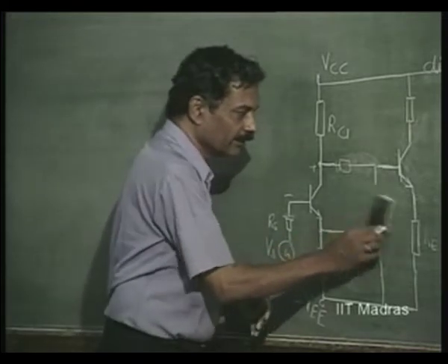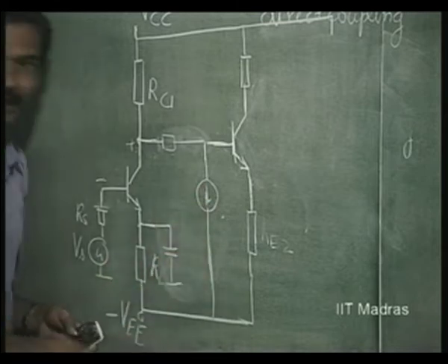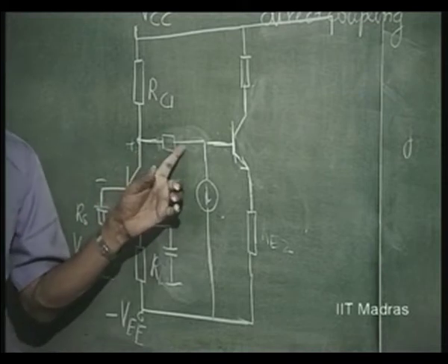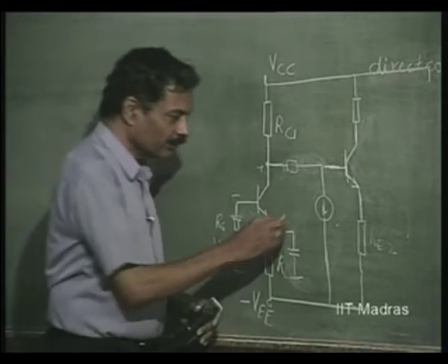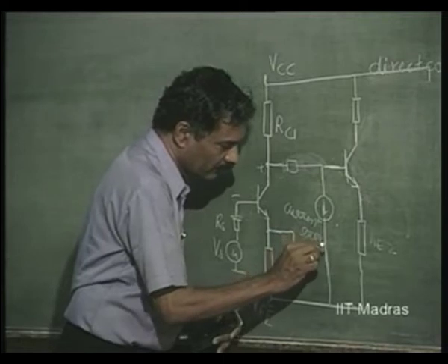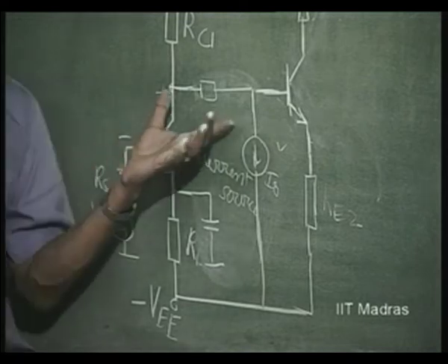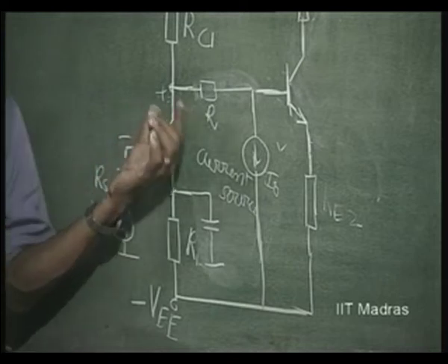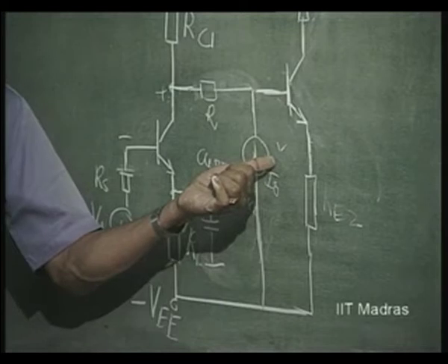That means, we can introduce a current source here because this is the one responsible for attenuating. So I put a resistance and a current source. So this kind of thing, again, if this is R, is going to drop the voltage by I naught into R. You can reduce it. These are called level shifting circuits.